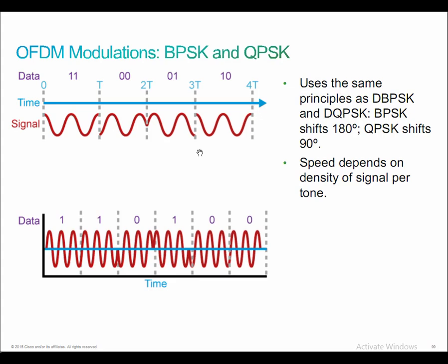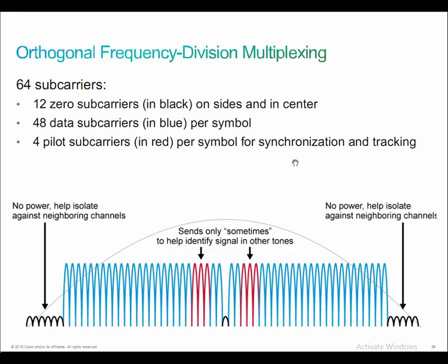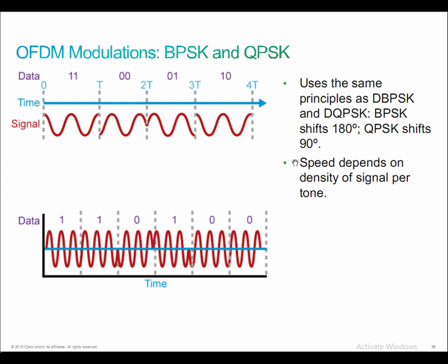But with BPSK, each carrier is 125 kilobits a second of information, which implies that we have 48 tones, as we saw on the previous slide here. These blue arches, I guess, for lack of a better term, represent the tones, which results in 6 megs of throughput at a minimum. All right.